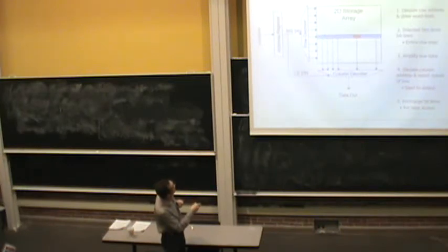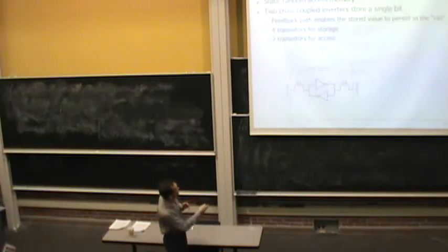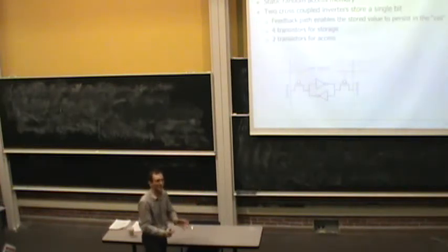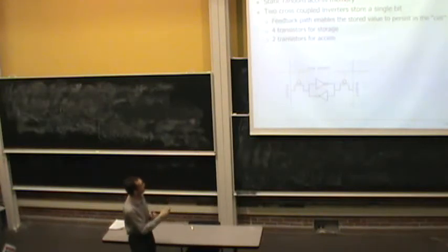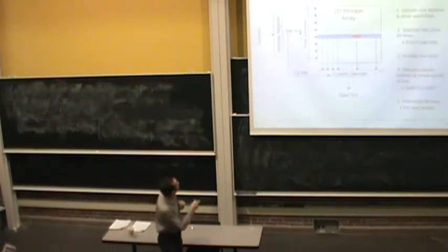This is your row. And you have a bunch of rows put together in a 2-dimensional storage array. So essentially you have rows and columns of memory. And you could define, let's say, each column to contain a number of these cells. For example, if you want to do a word access, you could define a column to contain the word access, which is 4 bytes, let's say. 4 bytes, right? So this is a generic memory bank structure. Rows and columns. It's a 2-dimensional storage array.